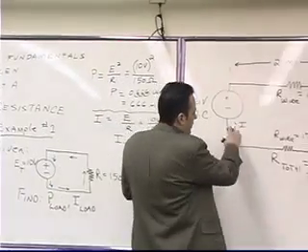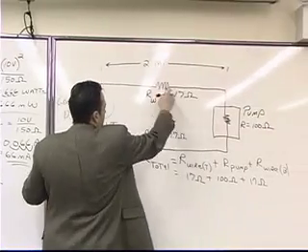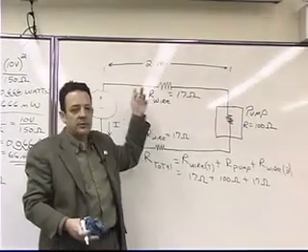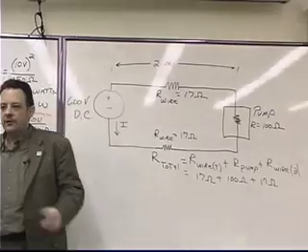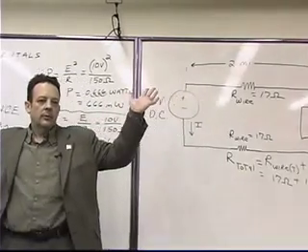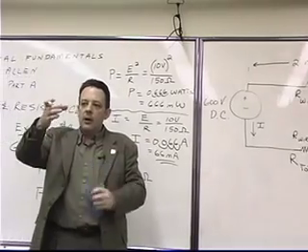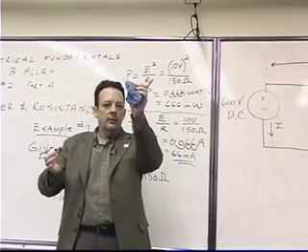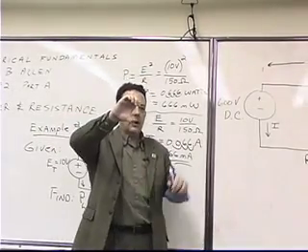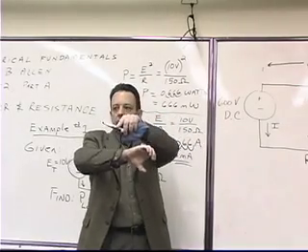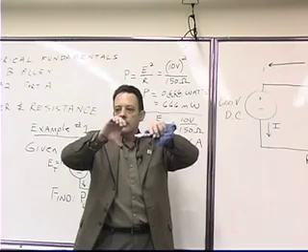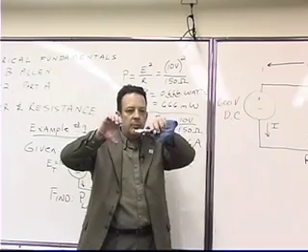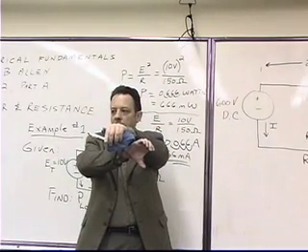So if we look at the current that's flowing in this circuit, would it be reasonable to say that the current through every component has to be the same? Yeah, because there's nowhere for it to branch off. Like in a water tee, you've got water coming in, and you can have water going out this way and water going out this way. With a water coupling, you've got water coming in and water going out because you're coupling two pipes together. That's like a series connection. So if you've got 5 gallons per minute of water flowing in this pipe, you've got 5 gallons per minute flowing in this pipe.